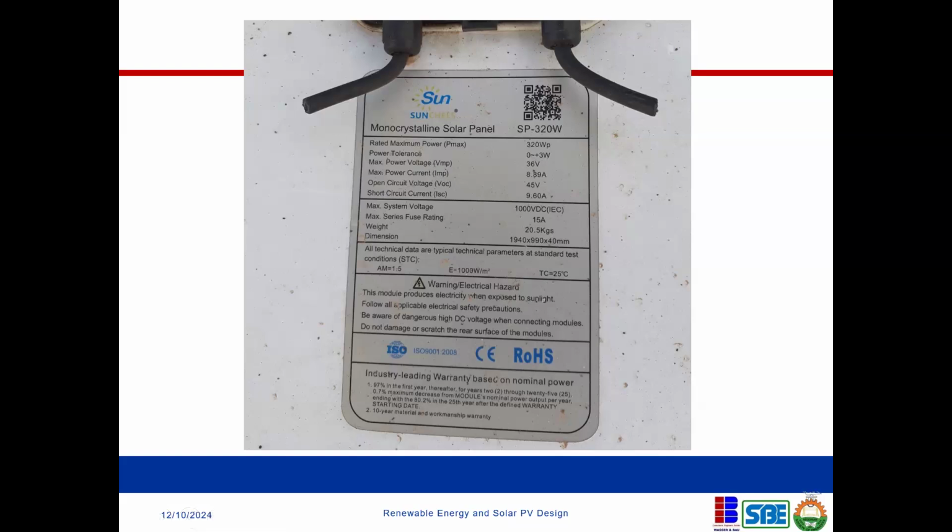In our first class, I talked about what MPP means, maximum power point. So at that maximum power point, this is going to be your voltage, and this is going to be your maximum power current. This is 8.89 amperes. Like I told you, solar panels are just in this range, maybe 8, 9, 7 amperes, and then the voltages. So this is just a technical data sheet of a solar panel.